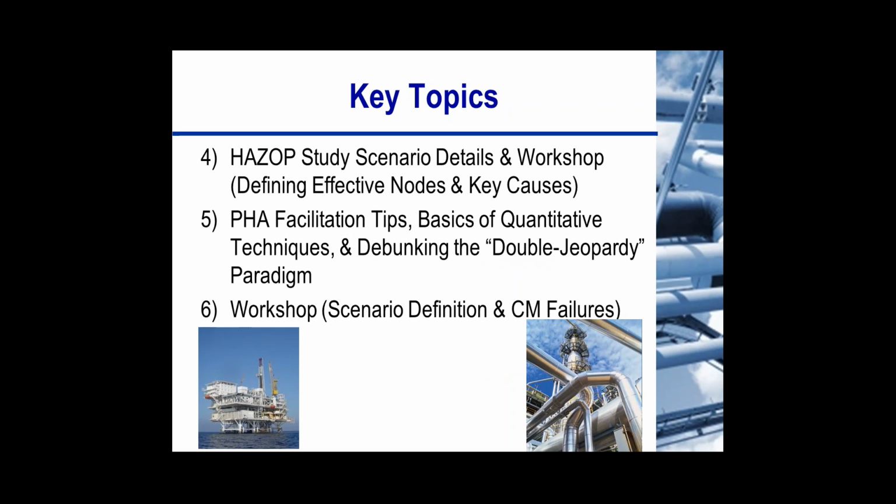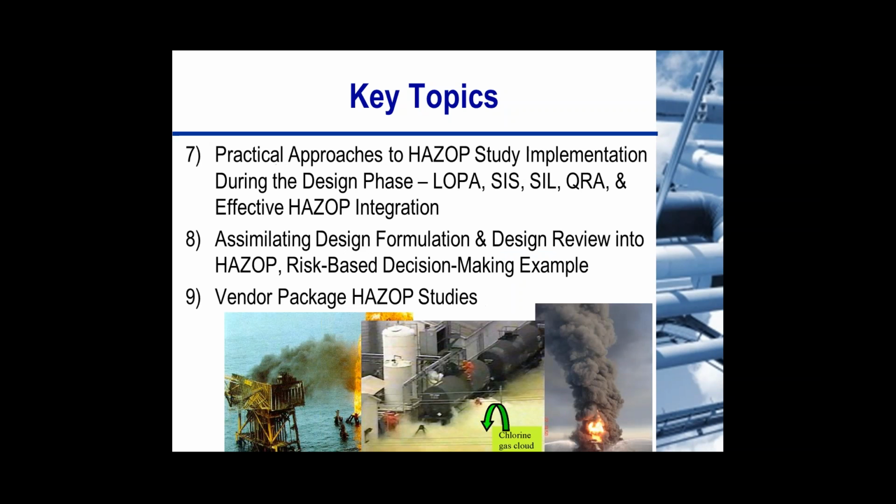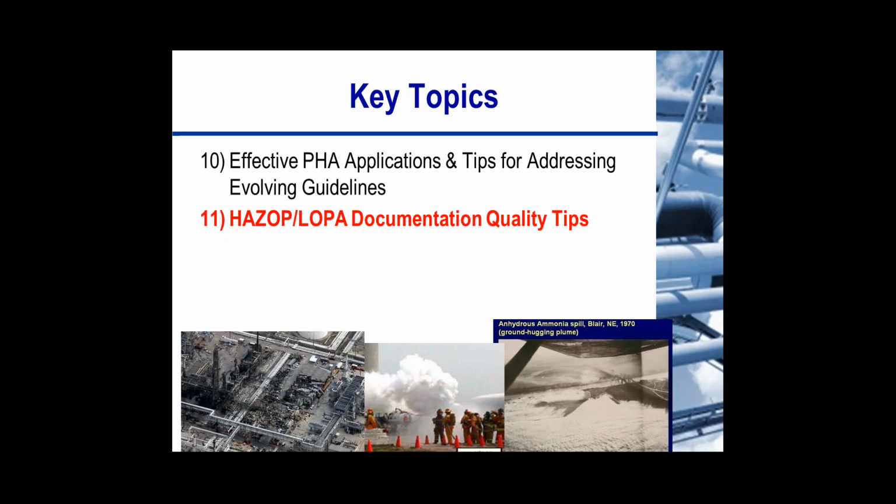Module 9 was on vendor package HAZOP studies. Module 10, which was the last one that we addressed, really focused on some of the evolving changes that are going on in the regulatory arena to address what were perceived as deficiencies in the overall process hazards analysis process. So in Module 10, we focused on what are those tools that are out there, HAZOP being the workhorse of the industry, LOPA helping you get a different slant on the scenarios that you define during the HAZOP to provide some more quantitative definition of things.